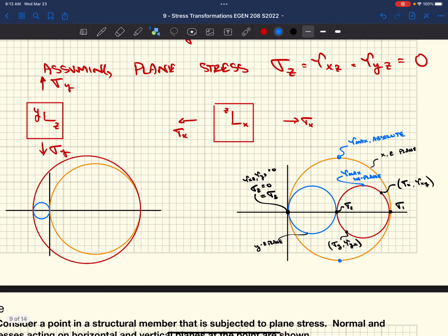So if our initial Mohr's circle, the xy plane we established, this red circle here, is all on the right-hand side of this axis, or all on the left-hand side of this vertical y-axis, then when we draw our three circles, we know the point that we're missing is always going to be the 0, 0 point, right? And so our large circle is not going to be in plane, because whether this circle's on the far right or the far left, we're going to make a bigger circle than our in-plane circle, right?